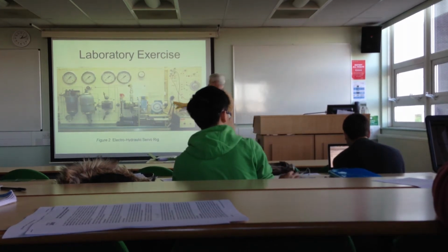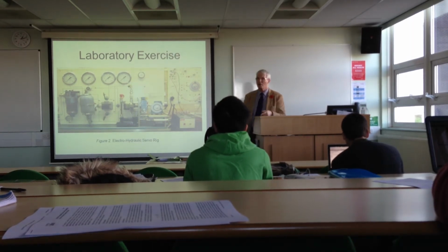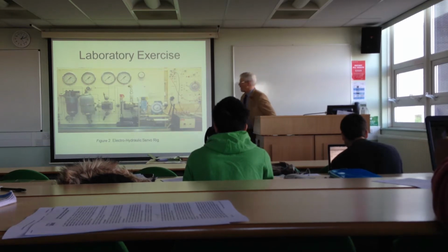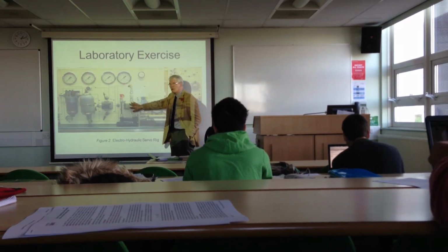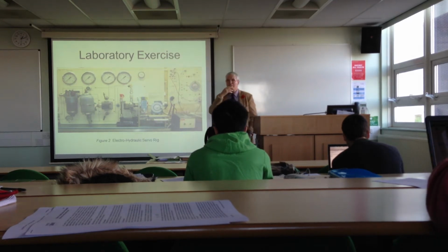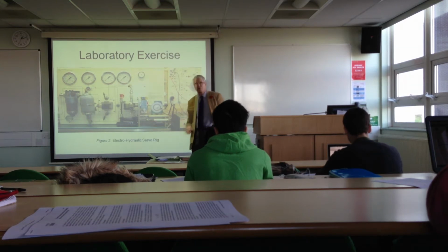We've got an encoder telling us how many revs the output has done. The computer knows that, knows how far the flaps and slats have gone out. If we, instead of using a rotary device, we used a ram, a linear device, then we need an electrical signal. And this is a linear transducer.